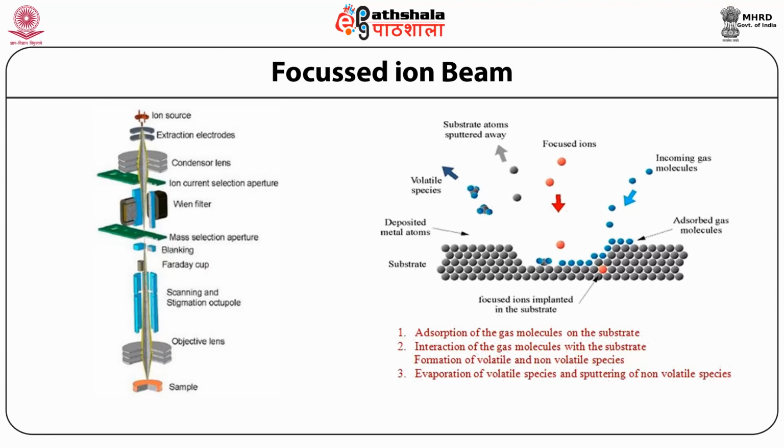So continuing our discussion over the FIB system, the left hand side figure shows the various components of the FIB system and the right hand side one shows a milling process in FIB. So as evident from this figure, the gallium, that is Ga+ primary ion beam hits the sample surface and sputters a small amount of material which leaves the surface as either secondary ions, I+ or I-, or neutral atoms N0.